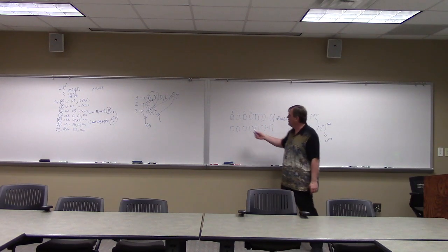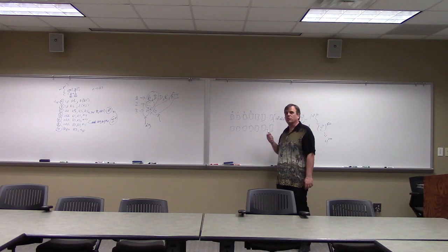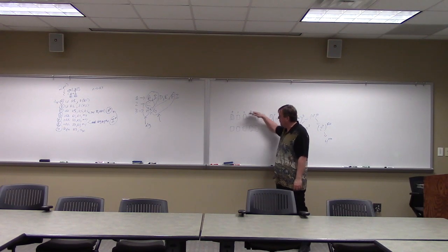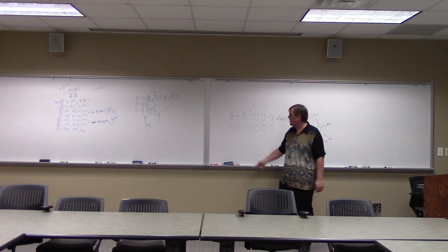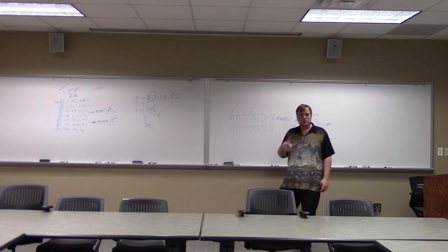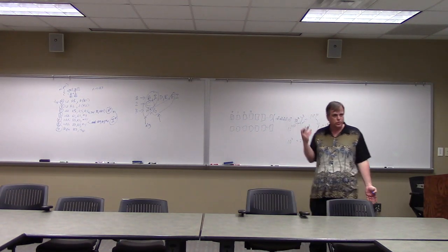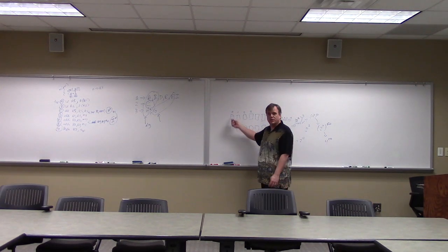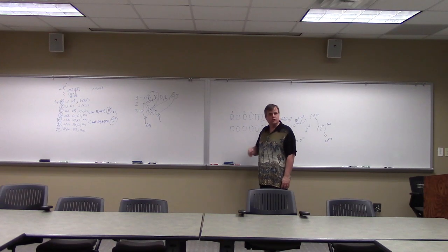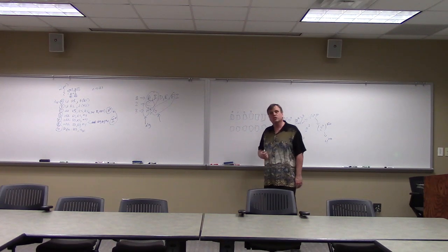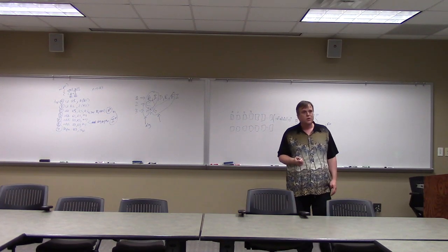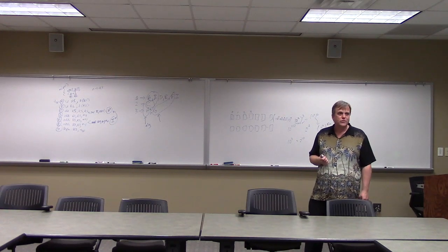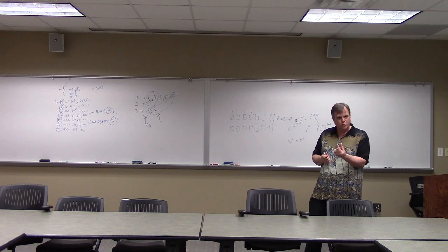But this required me being ludicrously parallel, like vectors. So anything we can put in this type of format, and just chunk, chunk, chunk, with little streams in here, we're going to call it a vector processor, because it's really good for processing vectors. And we can call these little things, each handling an individual stream that it keeps repeating, a stream processor. Well, welcome to a GPU. This is how GPUs are set up. Little tiny things we call stream processors.